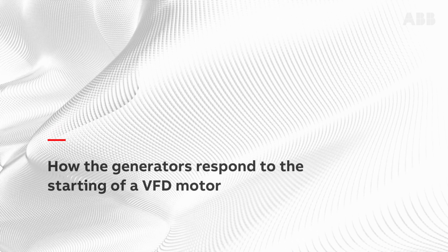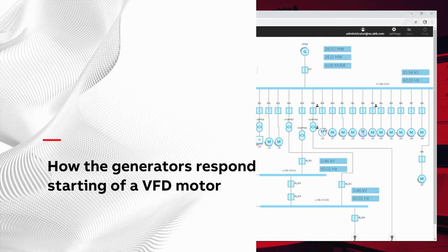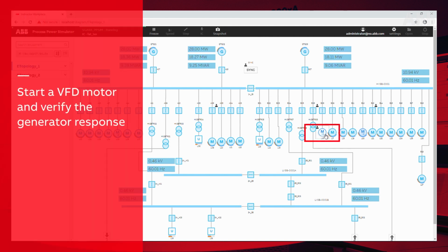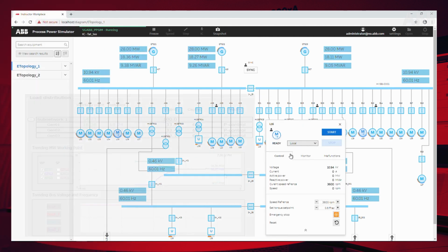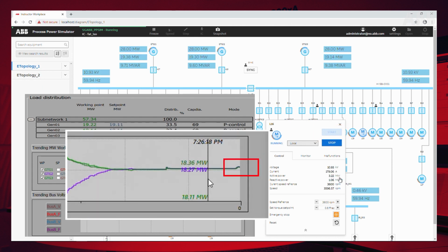Now let us see how our generators will respond to starting of a VFD motor. To start a VFD motor, click on a VFD, select start, and you can see the response of the generator. It's a smooth ramp, it's not a kick, it's a smooth ramp.